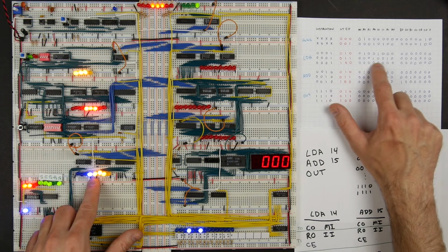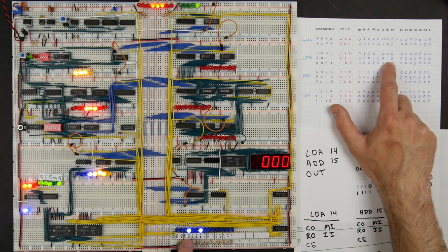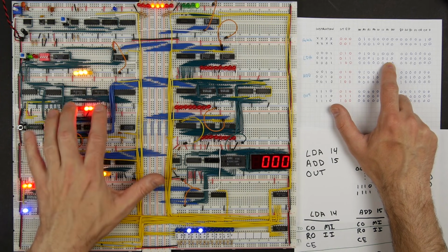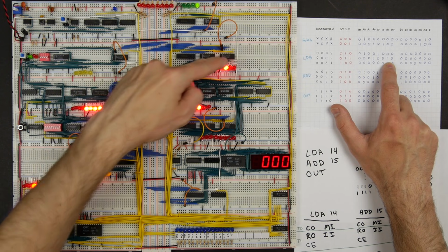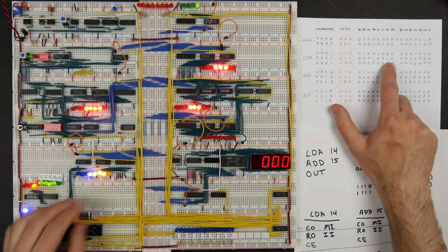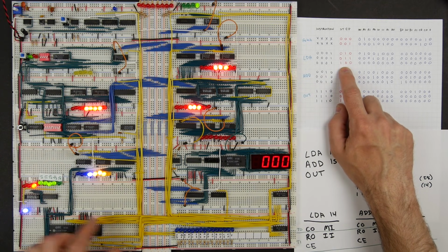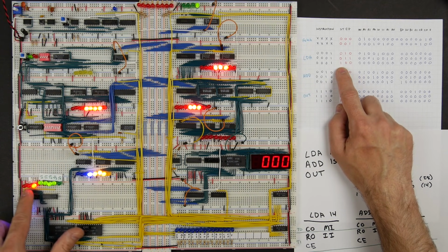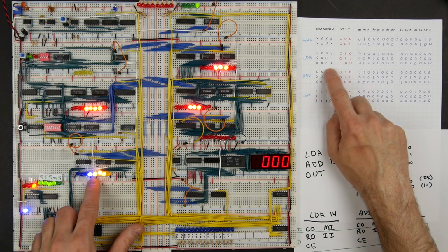And so now we should be doing a RAM out and A register in. So indeed, that's what we've got, RAM out, A in. So it should take the contents of RAM and put it over in the A register. So we'll advance the clock, and that's what happens. Puts that 28 over there into the A register. And then now we're on step 100, and our instruction is still load A, 0001.